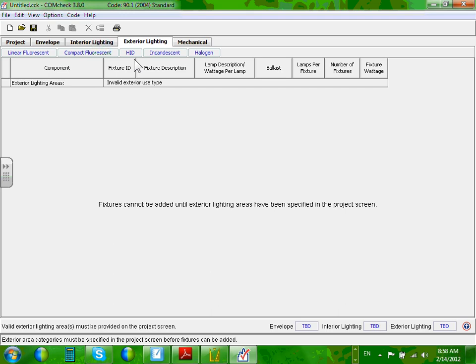Grab all the lights that we designed, dump it into this software, and see if we can meet ASHRAE 90.1 2004. What happens if we don't? Then you might have to go back. For our project, it's good. I'm not going to force you to. For other projects, you might have to go back and redesign the lighting system. What does redesign the lighting system mean? Put a smaller wattage fixture in the area. So it's all about watt.